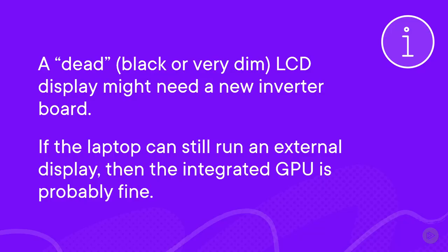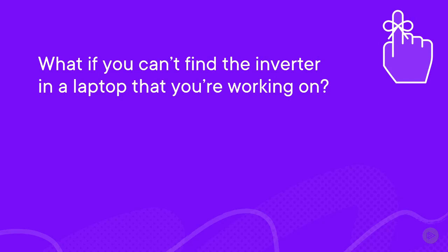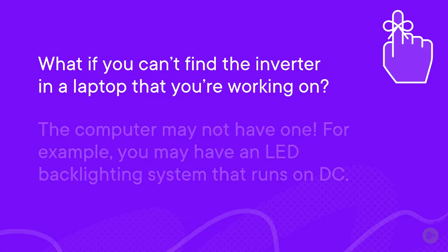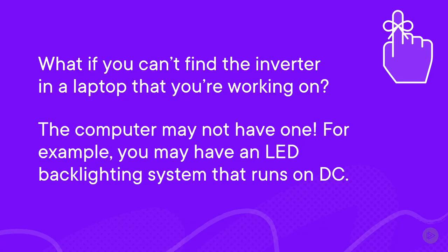Even if you do have to replace an inverter, it's usually not very expensive, certainly a lot less expensive than the display panel itself. I remember taking apart a laptop in the early days of LED backlighting, and I couldn't find the inverter board, and it was driving me a little bit crazy. And then I did a little bit of research and learned that LED backlit systems don't need an inverter board because LEDs run on direct current, just like all the rest of the circuits in a laptop. That's another benefit of LED displays, one less circuit board in the computer.